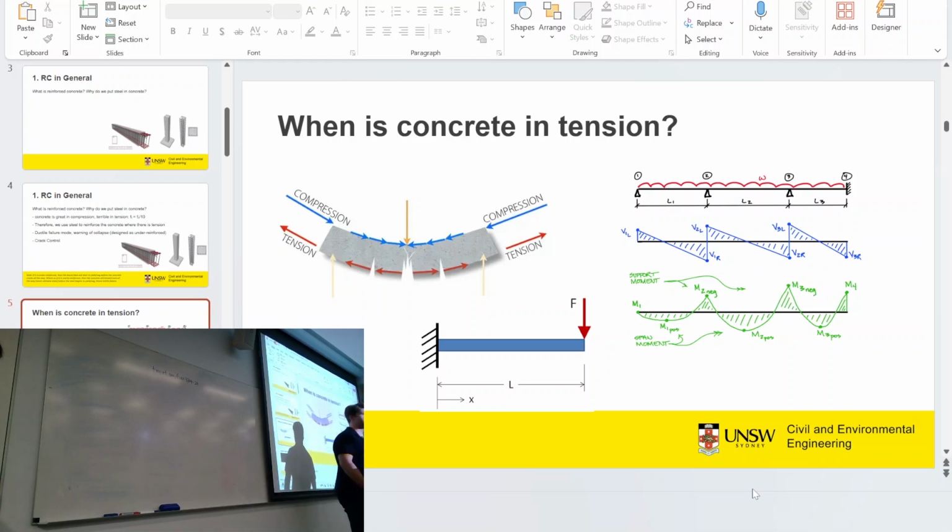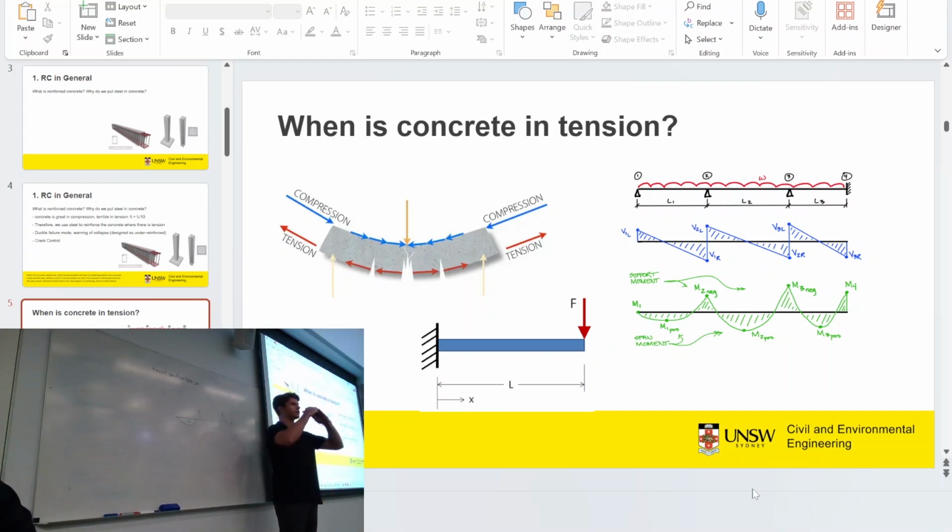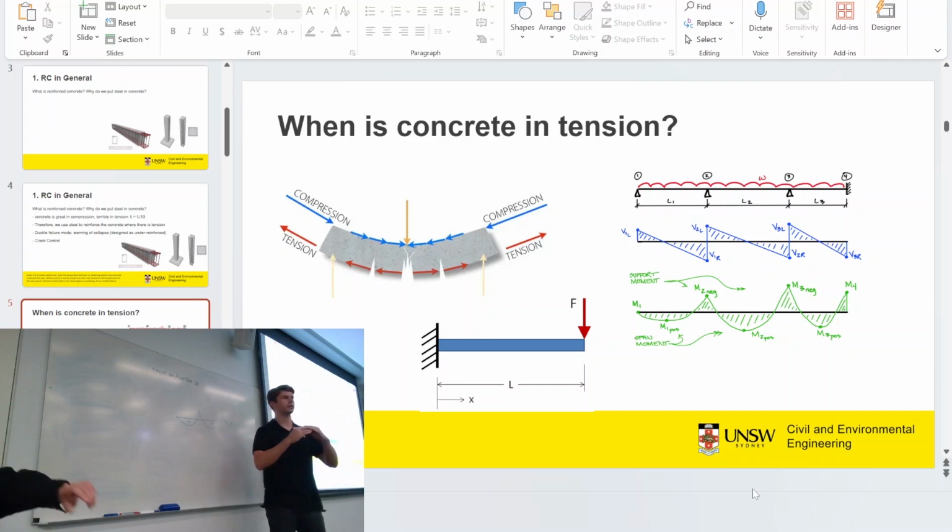And that's why in statics as well, you'll draw your bending moment diagrams with the positive on the bottom and negative on the top. Do you guys remember that from 2303 for bending moment diagrams? That's just to resemble what the beam will look like when it sags. So that's positive, positive, negative, positive. You've got hogging over here, so it goes up like this. So negative bending is just defined as the top face being in tension, essentially.